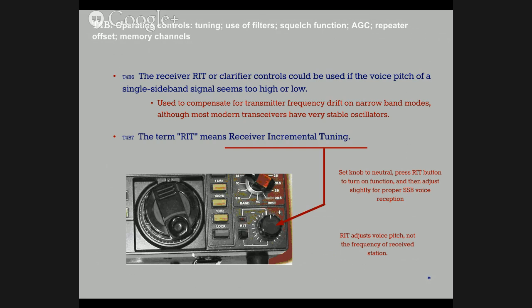But when you go to key the microphone, the transmit frequency will be whatever is dialed in. And this is generally used for narrowband modes, so single sideband, etc. It was originally put in because a lot of transceivers and transmitters had a certain amount of frequency drift.